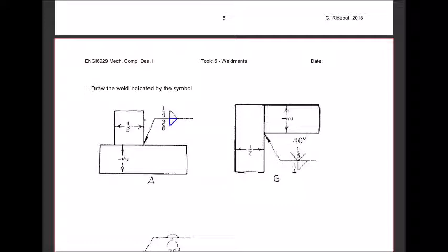So one of those triangular welds, 3/8 is about 3/4 of a half, so we'll have a fillet weld like that. Now the top of the line is called the other side. That's the actual technical term. So here the other side is around here, and now we need a 1/4 inch weld there, also a fillet weld. Okay, so there's the weld. Fillet, fillet. Alrighty.